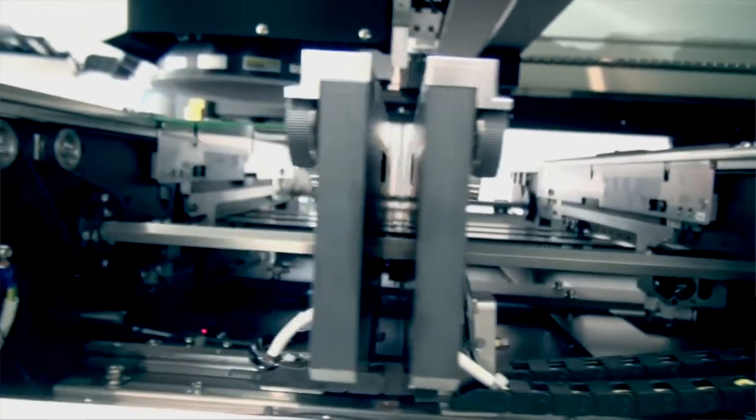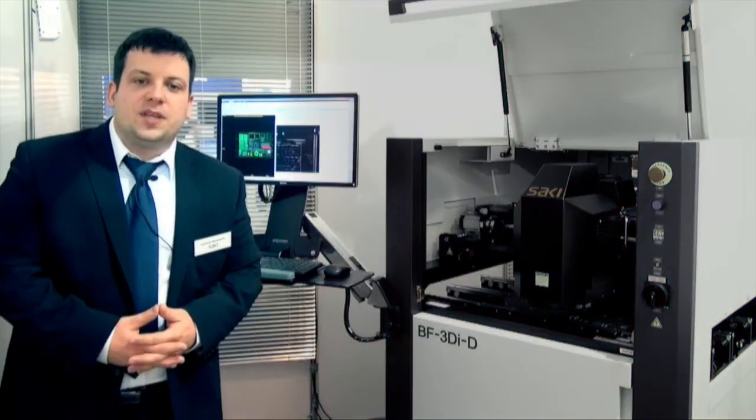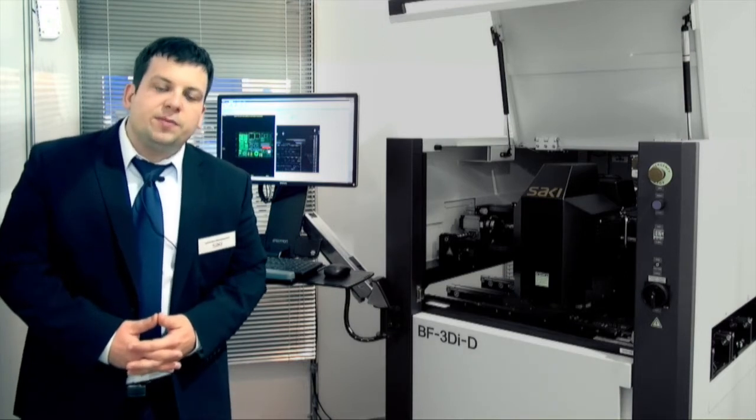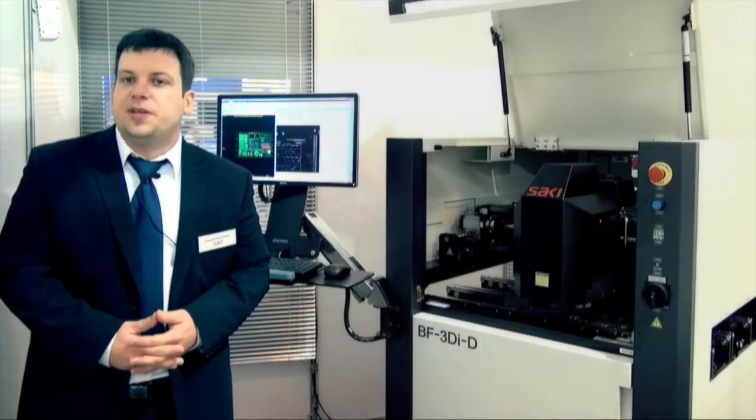The use of the machine is very simple. Let me show you how we can program the machine. As an example, we'll select a fine pitch QFP, and we will design the shape and recipe library. The shape library is the geometry of the package, and the recipe library deploys the inspection steps in there.